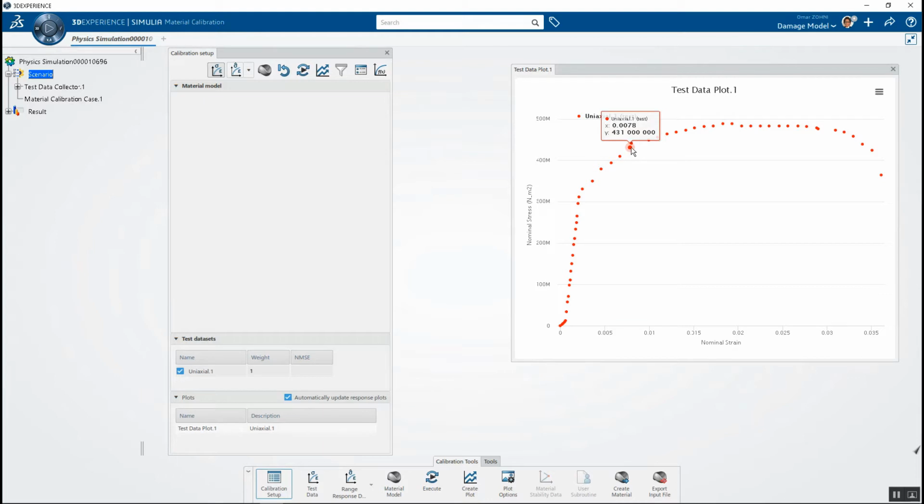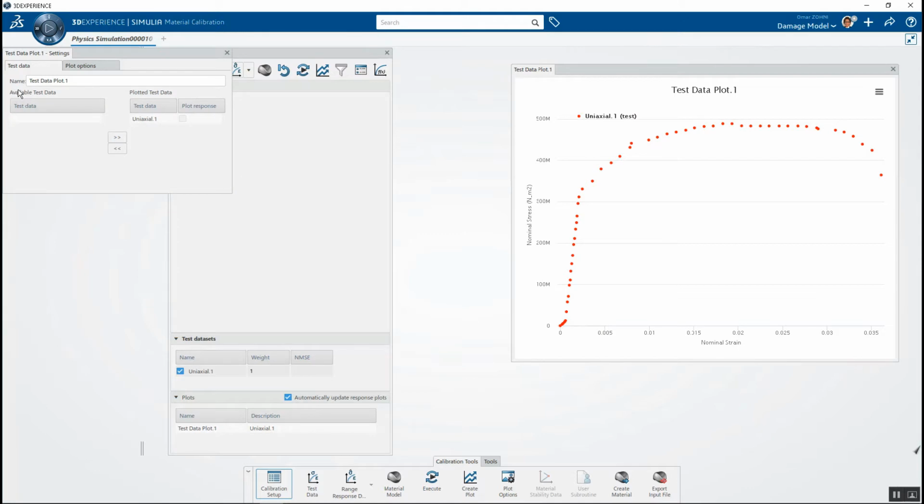And you can see some of the data that's unrealistic. Here's a point that's really close together, and then we're going to do a zero shift to account for some of this slack that's in the model. We also know that for this particular model, our Young's modulus is going to be about 205 gigapascals. We know the Poisson's ratio is 0.33. So we've gone ahead and imported the model. If we want to, we can change the way this appears. So instead of having it be red, if I come here to my settings, you can see I can change the name of it.